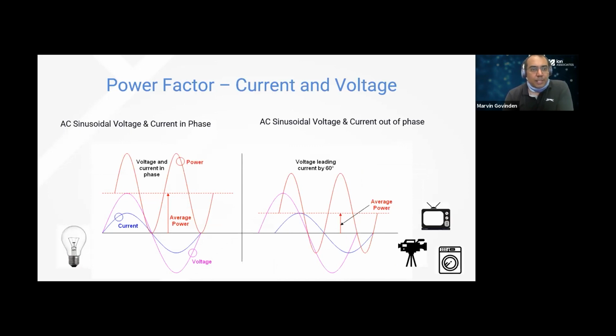What other things do we come across commonly now? Years ago, when there were only light bulbs that we had to worry about, an incandescent bulb has a power factor of 1. It doesn't have any issue in terms of changing the phase of voltage in relation to current. But as we've used power supplies, like switch mode power supplies, and motors, we have inductive loads.